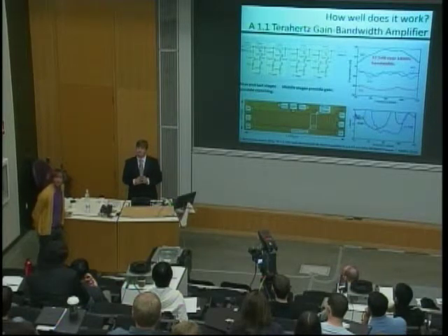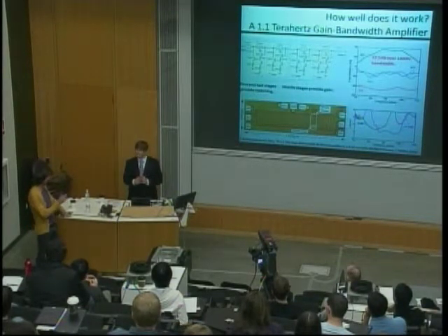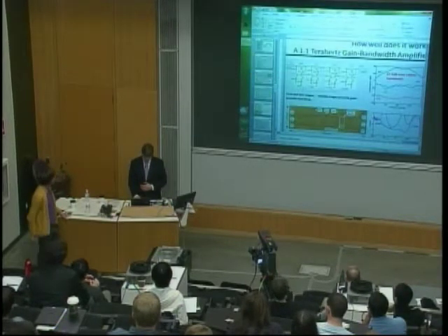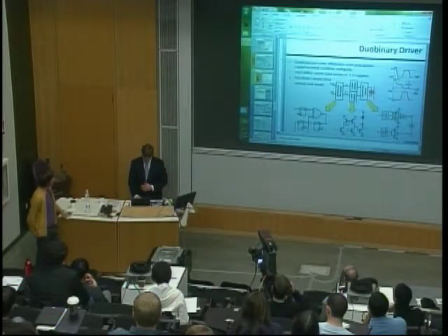Anyone else? So for your modulator, you did pre-emphasis where you momentarily jack the voltage above VDD or below. Why not just run it above VDD the whole time? What's the trade-off? CV squared.